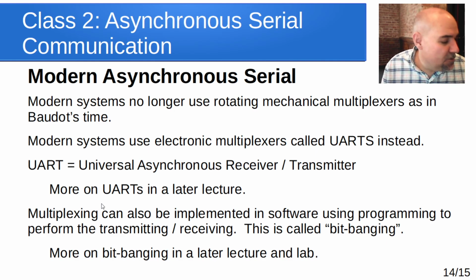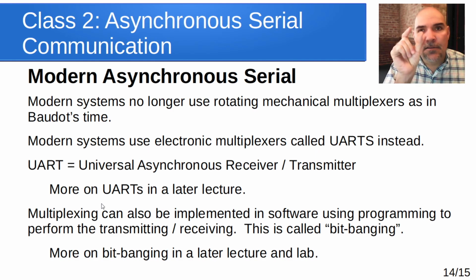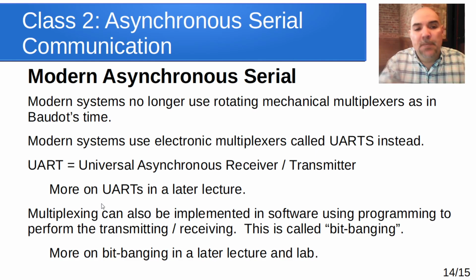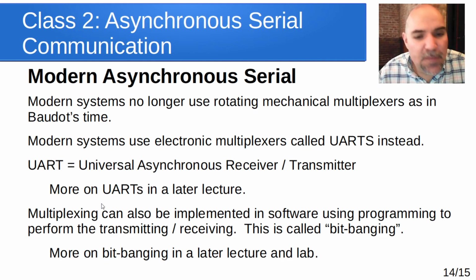And actually the same kind of thing is used in wireless systems. It's just rather than time division multiplexing sharing a single wire, they're sharing a frequency band to put data out over a wireless system. So if you see TDM associated with some kind of wireless system, time division multiplexing, just note that it's dividing up the message into bits. It's putting each bit into the wireless spectrum one at a time to form larger messages from that. There are other methods for encoding the data as well that we're going to see going forward, but that's it.